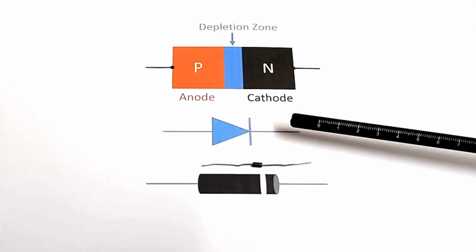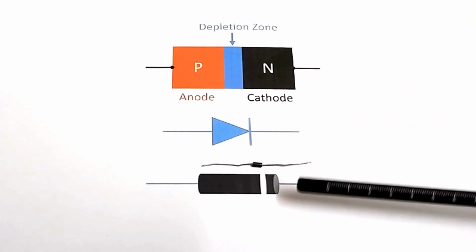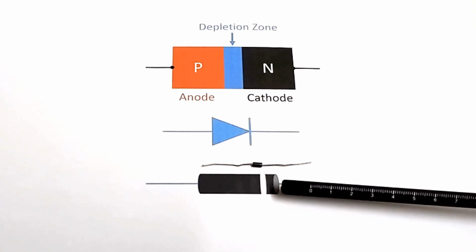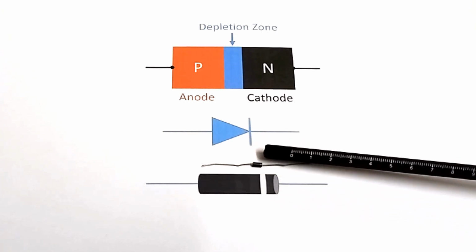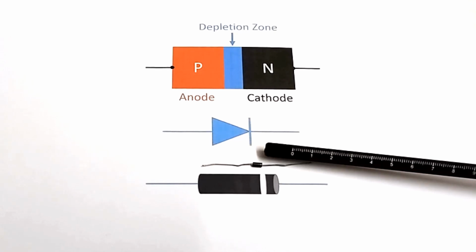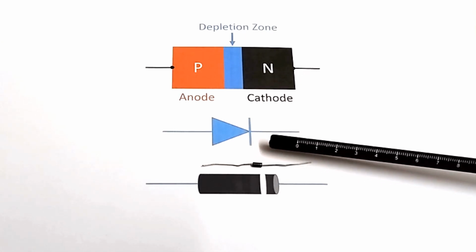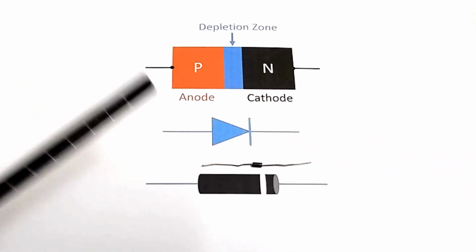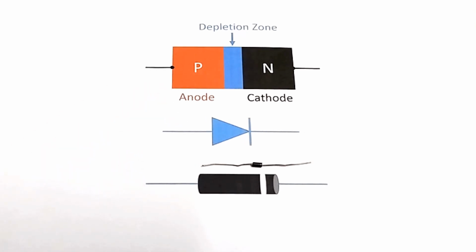This is the electronic symbol corresponding to the diode. Then this is the blown-up picture of the diode. You can see that there is a ring at one end, or a marker, which you can see here also, but this is a real diode. The marker is very tiny. If you are careful, you can see it very well when you look directly. This is a rectifier diode, and this will be the cathode, and this will be the anode of the diode. So this basic information is needed.